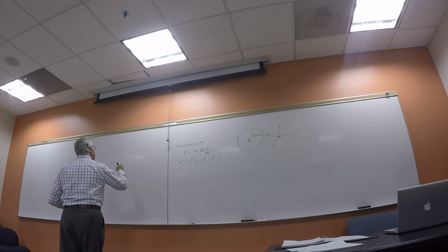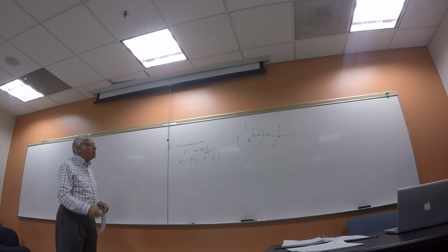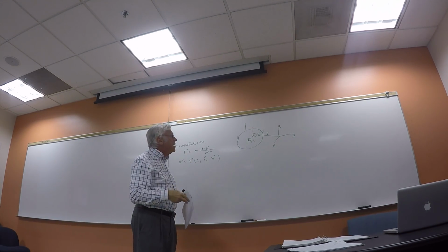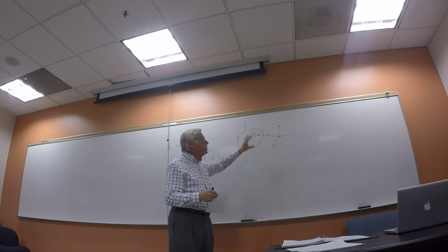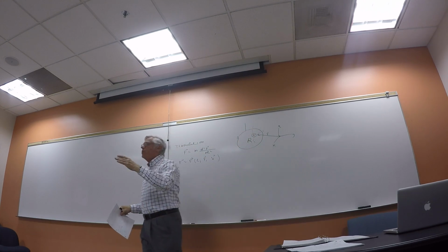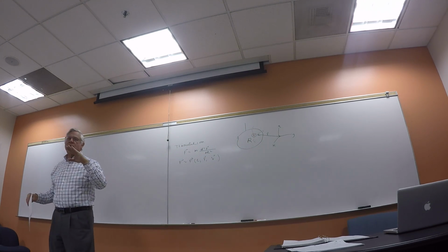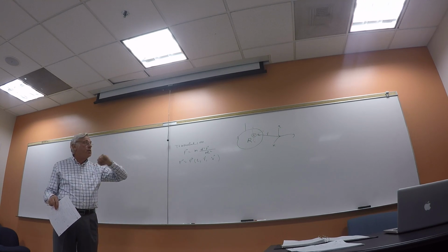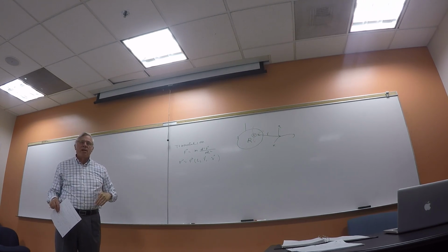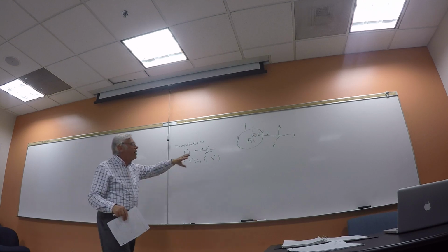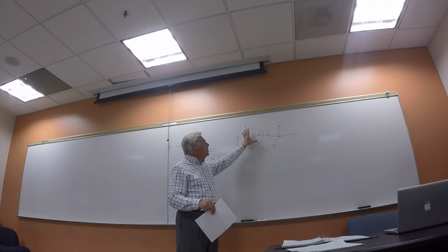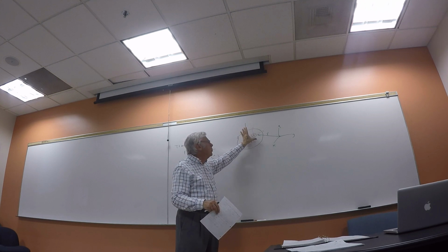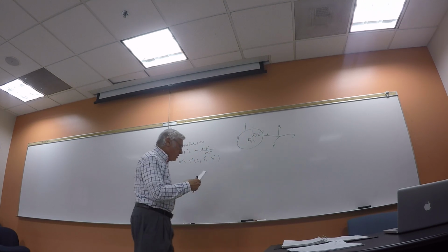We have Euler's equation of rotation. Okay, what happens is that there's a well-known result in rigid body dynamics that if you have a rigid body and you go to the center of mass, you can find what's known as principal axes of inertia. Usually the inertia, so-called the inertia tensor, is a 3x3 array. It's symmetric, but it has off-diagonal elements, okay? But you can always find a set of what's called principal axes in the body. You'll do this also when you do mechanics of materials. There'll be so-called principal axes where the inertia matrix is diagonal.